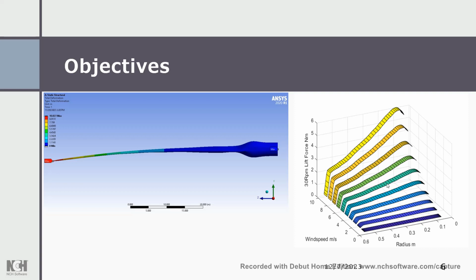The application of fatigue analysis is instrumental in averting premature structural failures and damage. So when you evaluate the stress levels and load cycles and cyclic loading, this can help you accurately produce reasonable results of durability and longevity of the turbine itself.